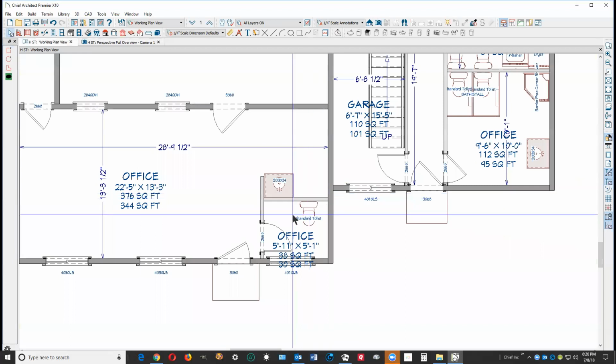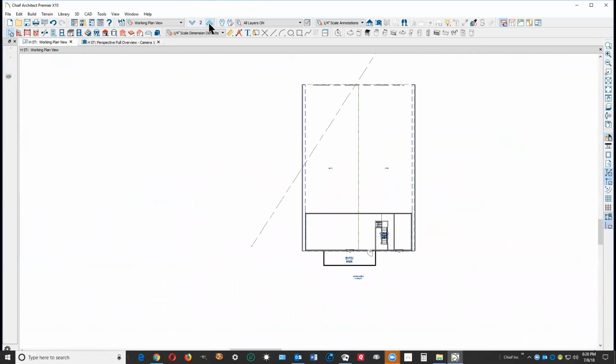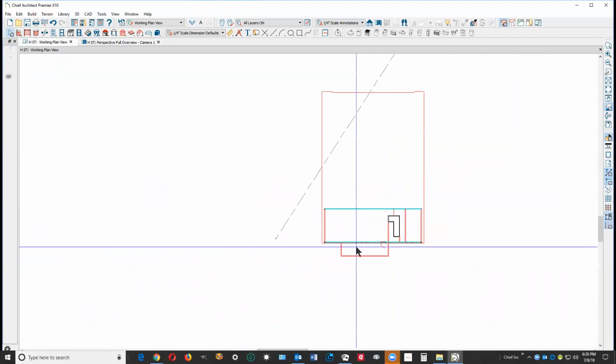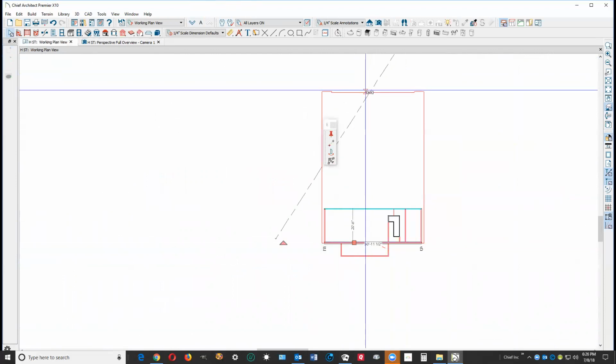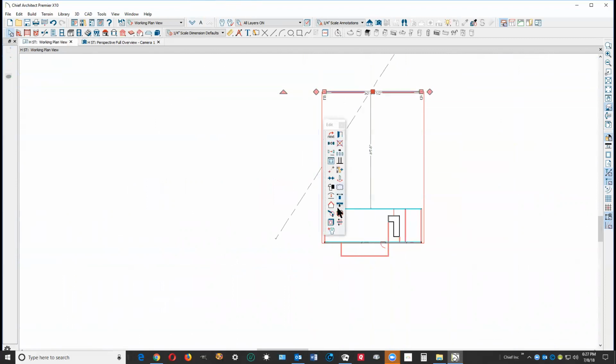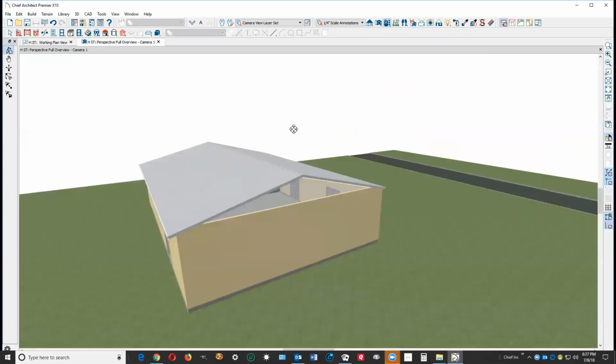Let's go to the attic and see what's going on with that one. The A level. Yeah, see, there's no wall back there. Let's turn on the reference display. Now I'm just going to take this wall and copy it and paste it back here. And then I'm going to flip the layers so the exterior layers are facing outward. And then I didn't get it exactly in place, so we'll align it with the floor below. Okay, let's save, then go to the Control tab to go back to the overview, and that should, uh-oh.